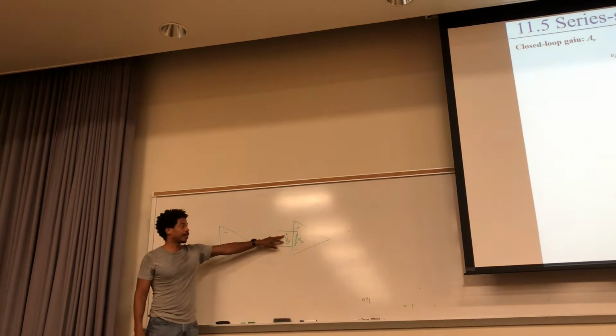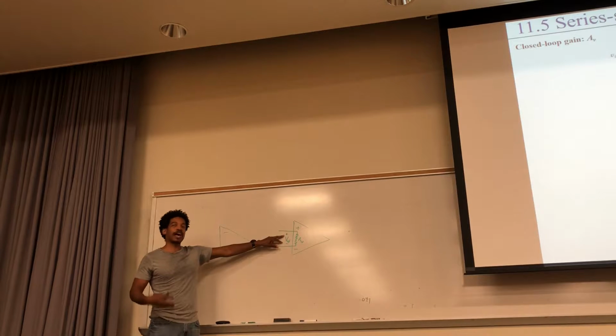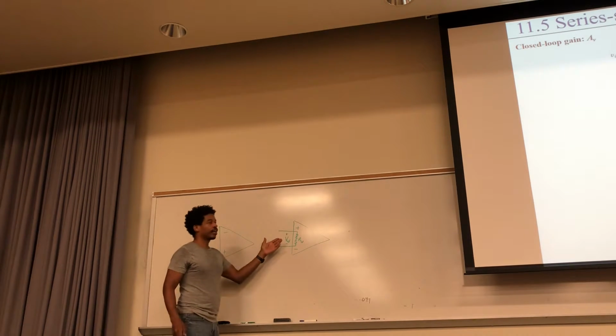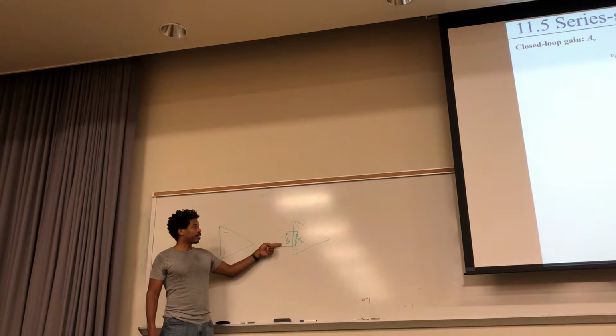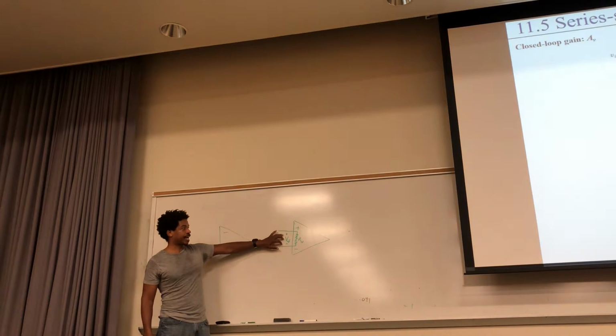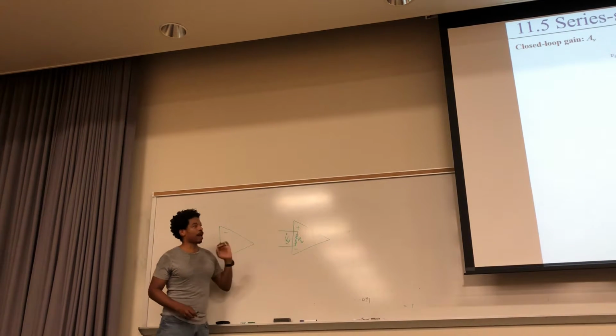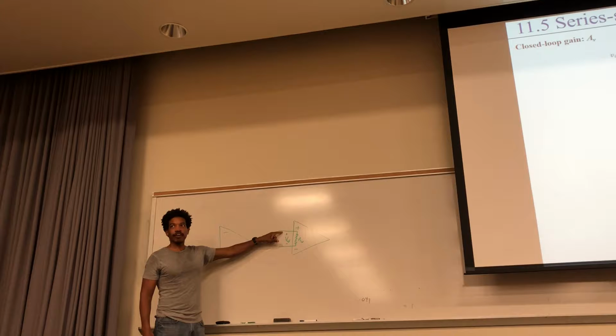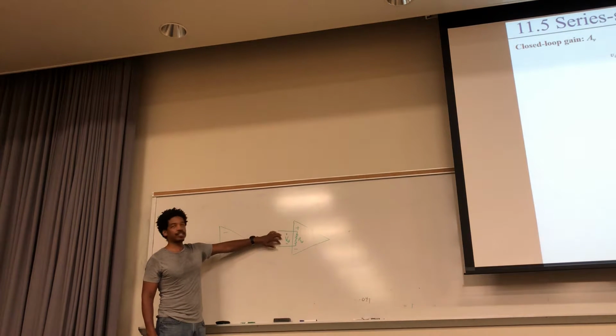That makes a big difference, because remember a few lectures ago we were talking about the importance of having your sign convention in your circuit, because if someone just said the voltage is whatever across here, you don't know if the voltage is going from this direction to this direction, or this direction, without a picture of the symbol, right? This gives you your positive sense. So if I said the change of voltage across this op amp was 3 volts, then you would say, okay, whatever that voltage is down here, this one is 3 volts higher. But that's because you see the positive sense.